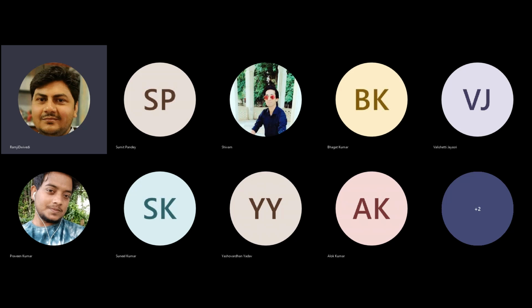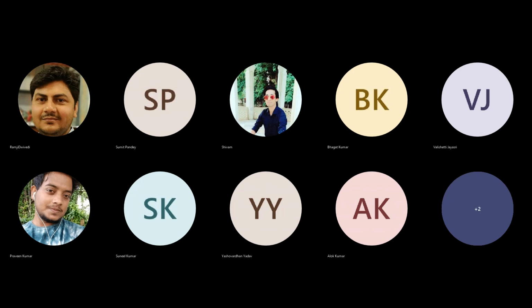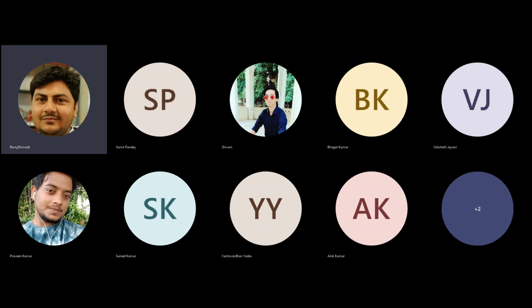Now, you have all seen in your previous course that you can develop a v is equal to x minus l kind of model, isn't it? Your GPS has that backbone. The least square adjustment is the backbone of any GPS system in the world. Why? Because you have the data set, you have the observation file, and you just have to fit in the model. So we'll discuss how that model can be prepared for pseudo ranges and carrier phases. We'll see details about those mathematical models, from single versus relative, static versus kinematic, real time versus post mission.